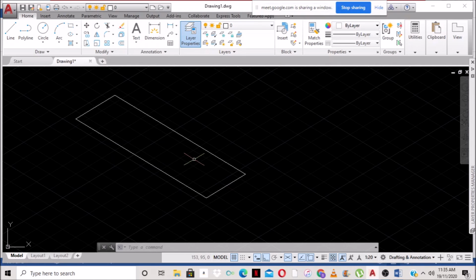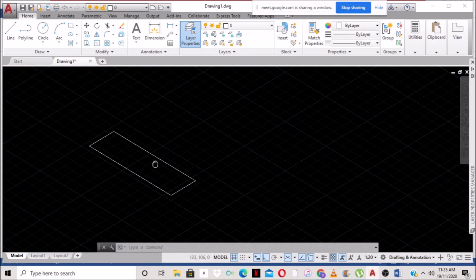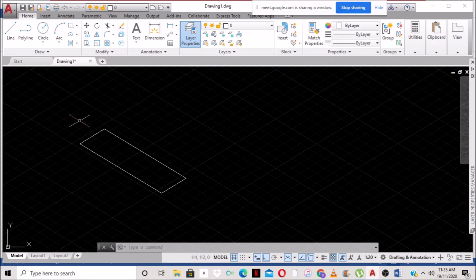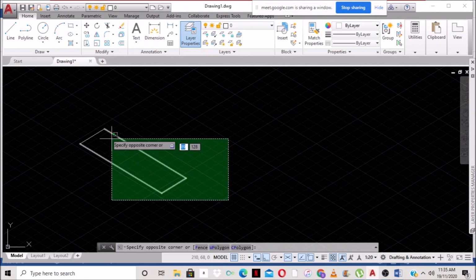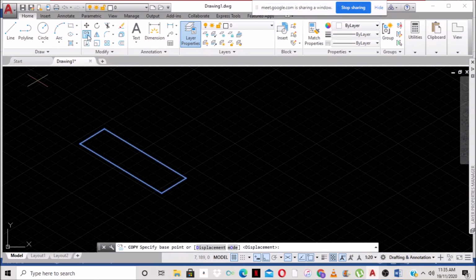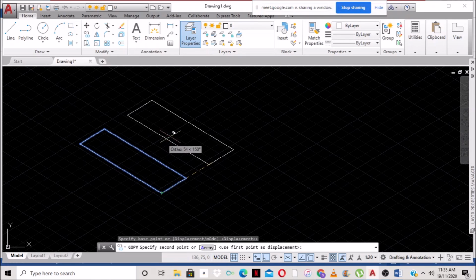Yes, sir. All right. So now, as I said before, in order to move with speed, all we can do is copy this rectangle. We select a point in the join area and move over the join, so all of the join is highlighted. We select copy, then select our start point where we want to start copying from. But we've seen that we can't move up. We can only move to the back and to the front, and to the left.